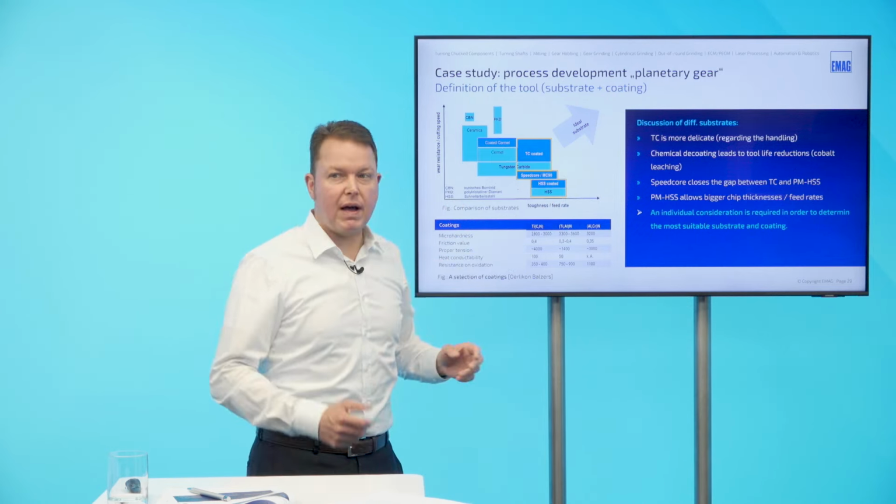There is a rule that says the helix angle should not overstep 6 degrees in case of having straight gashes. Why is this the case? Simply because otherwise we would get deviations in the profile, and in order to avoid those, we should accept not to overstep the 6 degrees. Well, one might overstep this.